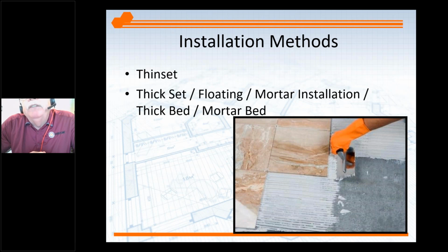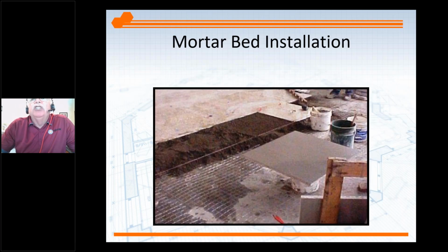That's why generally we have to come in and grind or self-level those floors, because concrete's never truly flat. It gets expensive to really place it flat, and as it starts to go through its life cycle, sometimes you'll see it curl, warp, and that's why this is probably used most, about 80% of the time. If they're using a mortar bed installation, this is a traditional method, cement and sand mixed on site. This is out at the Seattle-Tacoma Airport.